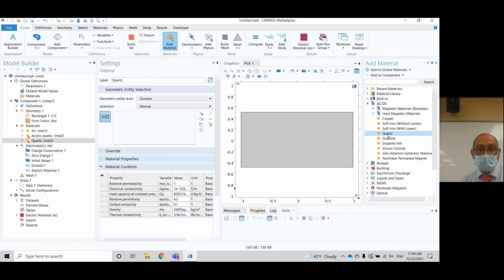Quartz. Oh, that is. So here we have a relative permittivity of 4.2. Okay, so what will happen? What will happen if you have this cavity and then you put a different dielectric inside? What happened to the electric field? What happened to the electric potential? Larger permittivity, decrease it. So we will expect that. We were working with something that just had like a 1.5, right? Yeah. So 4.2.